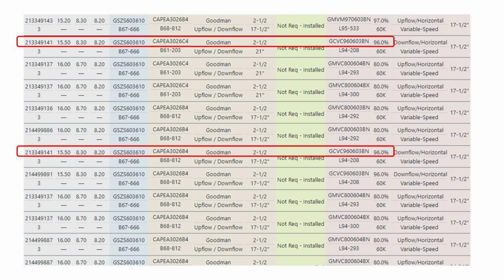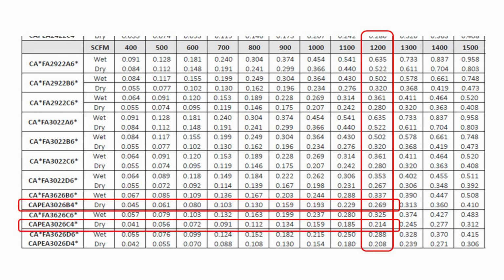And you'll see the two coils you have, a C width and a B width. And there's nothing wrong with expanding from a B width to a C width. We like the flush fit, but sometimes gaining that little less static pressure helps us choose a better filter. Especially when we're talking a high efficiency filter and the numbers we have listed aren't loaded. Once we load that up with some dirt, our external static pressure will increase.